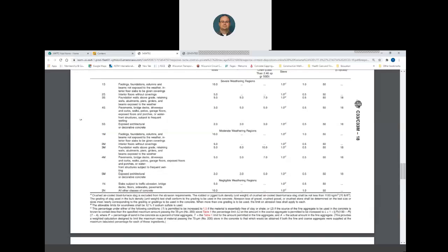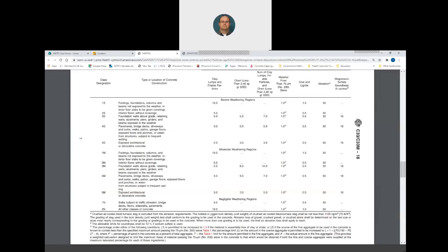All right, so that's like a formula. Don't really worry about this guy. So normally we want to stay in here because we're not essentially free of shale. Okay, so 1%. I've never used this formula in my career, but what this is saying is a way you can increase the fines depending on your fine aggregate. All right, so we want to hold it to 1.0%.